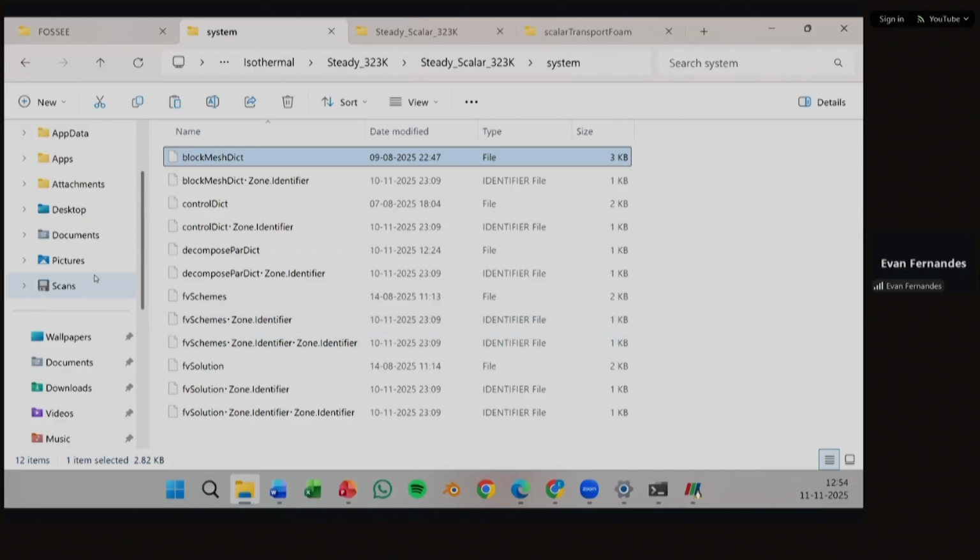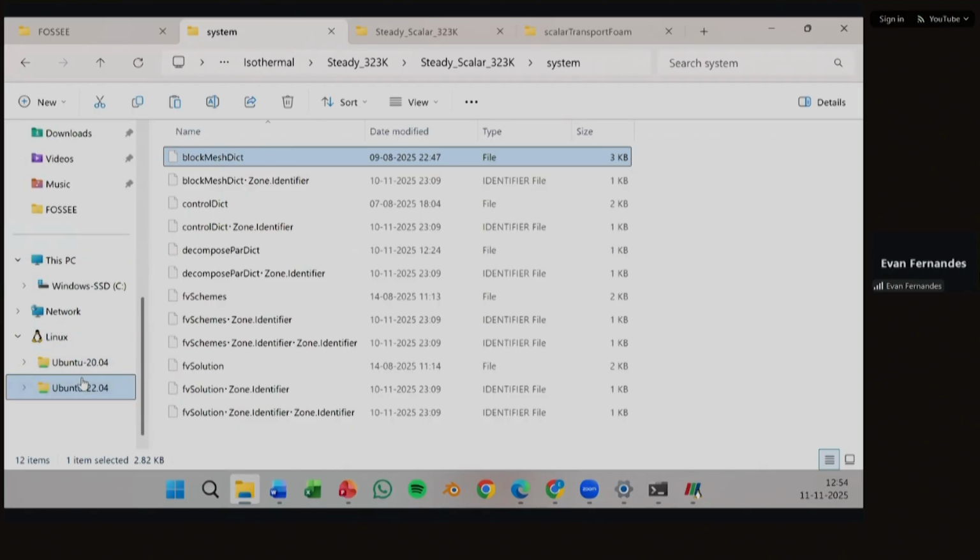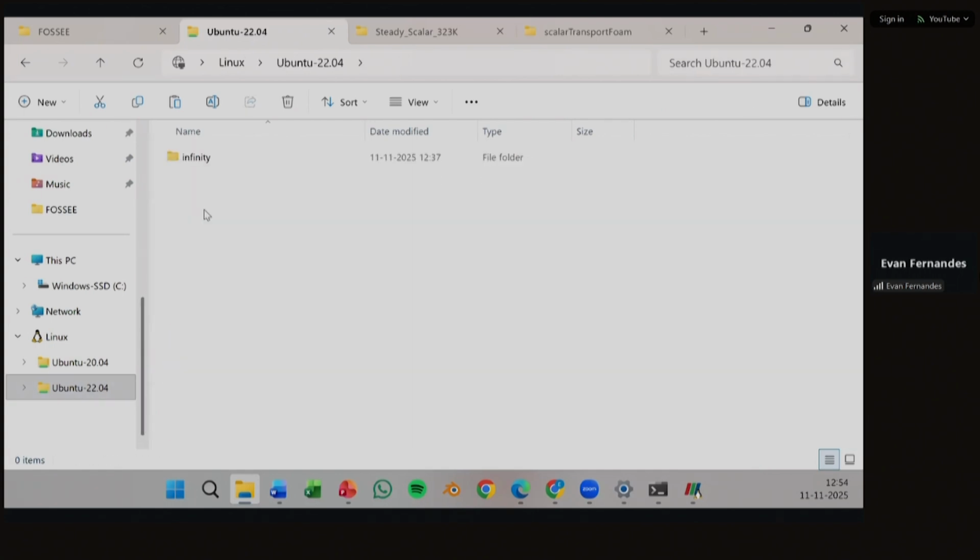That causes an error with Ubuntu because you cannot have any spaces in your directory. That's why it is always advisable to copy everything into a run directory, because that segregates which versions you're using. For OpenFOAM 2412, you have one particular directory. Let me show you. If I open home, over here I have OpenFOAM. You see I have multiple versions.